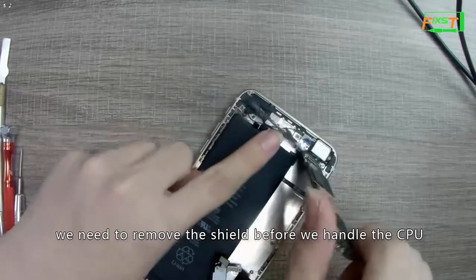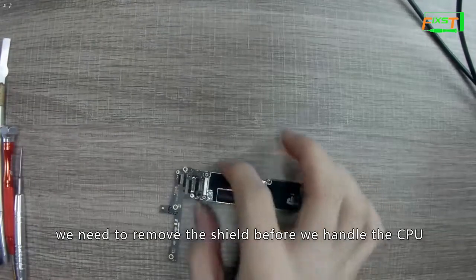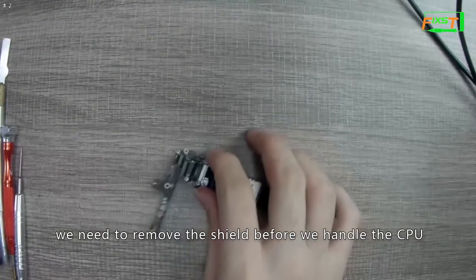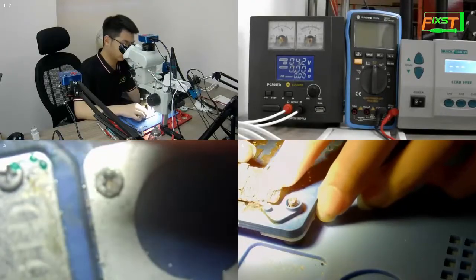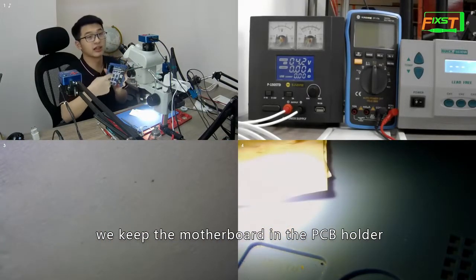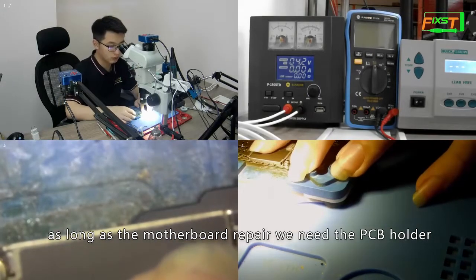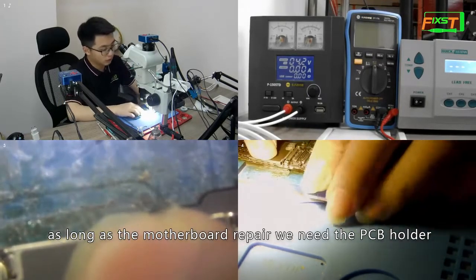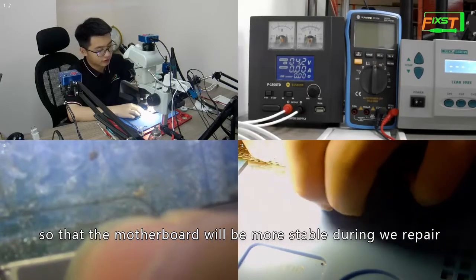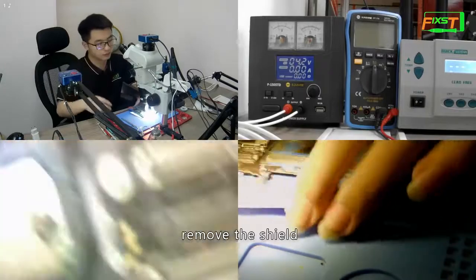We need to remove the shell before we handle the CPU. We keep the motherboard in the PCB holder. As long as we repair the motherboard, we need the PCB holder, so that the motherboard will be more stable while we repair. Remove the shell.